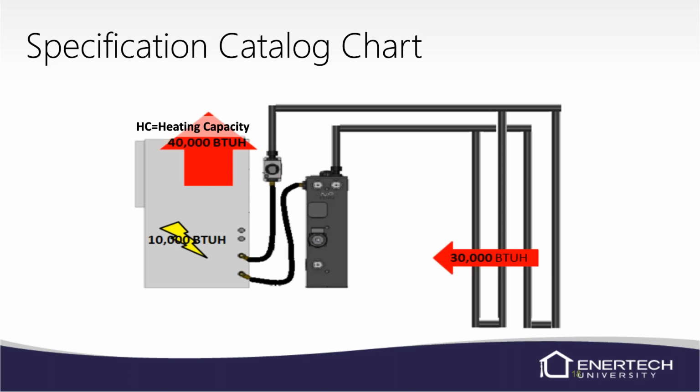So with this number, we could actually figure out the COP on the unit, how efficient the unit is working. So if you ever have a homeowner that's complaining about high bills, we can actually run this number and figure out what the COP of the unit is. We can compare that with the manual, and see what AHRI said, or our engineering data says it's supposed to be. And if it's pretty close, then we know it's not the unit that's causing the higher bills.